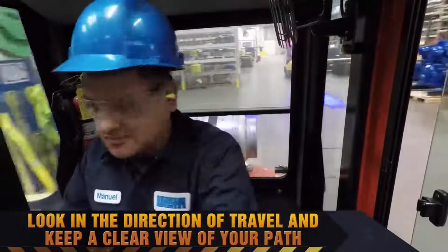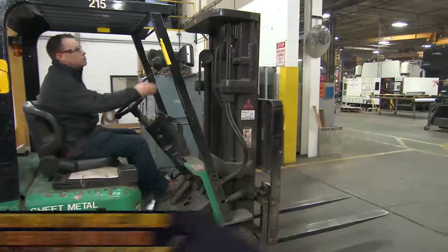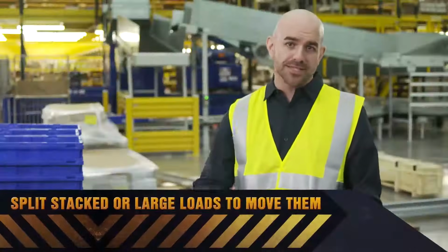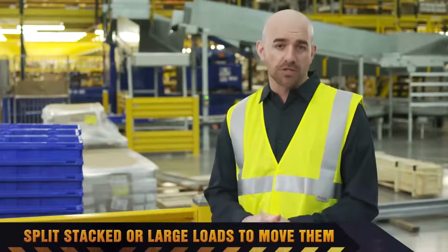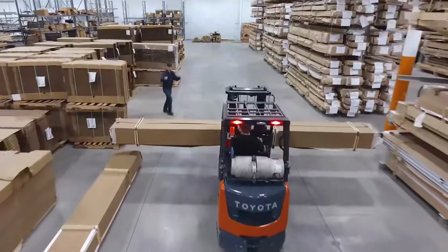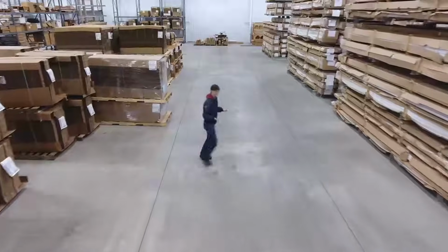Look in the direction of travel and keep a clear view of your path. If your work area has convex mirrors at corners and blind spots, use them. Sound your horn at corners and blind spots, and then proceed slowly. Remember, pedestrians always have the right of way. Split stacked or large loads to move them. If you can't split the load and it blocks your view, travel in reverse. Use a spotter or both. Spotters are there to quickly notify you of hazards.